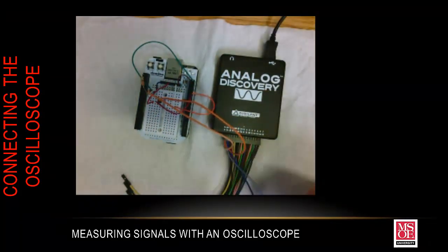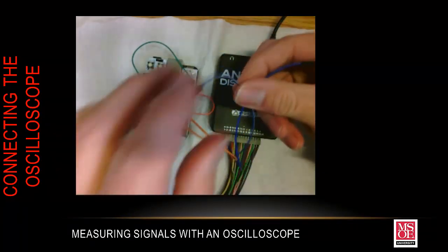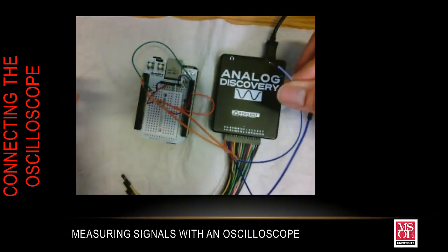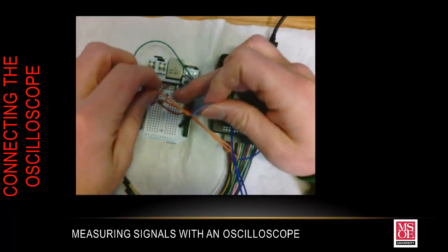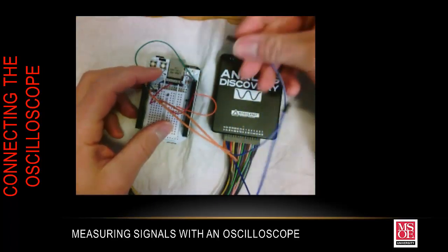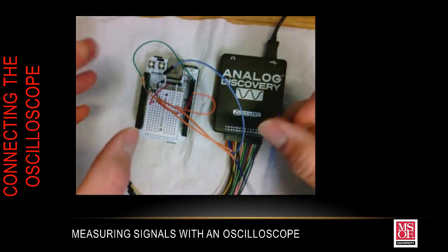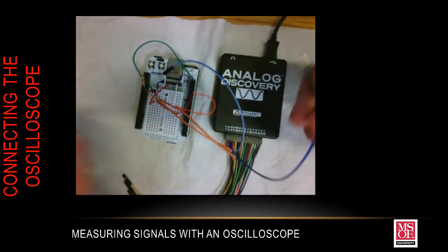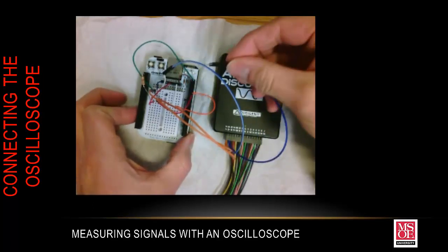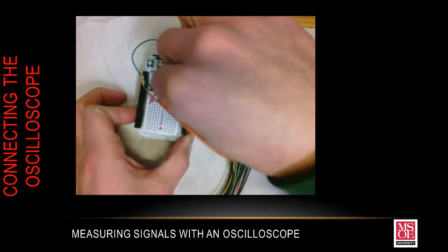Now the next two lines I'm going to connect up are the blue lines here. So I want to connect again this blue line with the white wire on it to a ground connection, which I actually have left over here, this white wire kind of hanging here. I'm going to plug it in like so, because I don't have another one of these adapter pins. And I'm going to take the other side of it here, and I want to plug this into actually where the LED is that's turned on, which happens to be right here.